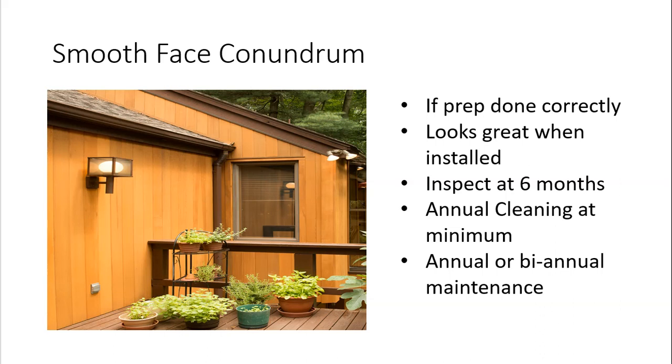If you're going to project smooth face, natural wood look, transparent or semi-transparent stain, it is not realistic to budget more than 2 years life out of the stain on the smooth face, unless you take some other considerations. Okay. We're not going to go into that. We're talking about basic stain expectations at this point.